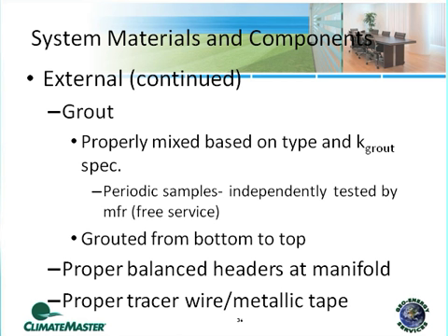But if you do have grout, anytime any of it needs to be mixed up, it's important during the installation to take periodic samples and send them to an independent laboratory for testing, to make sure that the thermal conductivity you specified for the grout is being met by the contractor. That's a pretty simple thing to do. You also want to make sure that you see the guys grouting the boreholes from the bottom all the way up to the top. We never want to grout a borehole from the top down to the bottom because it might bridge itself and create gaps or pockets in there.